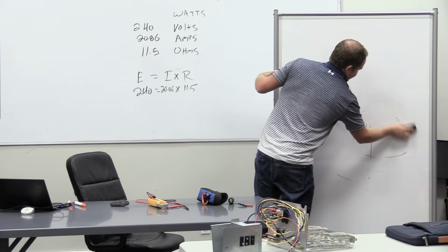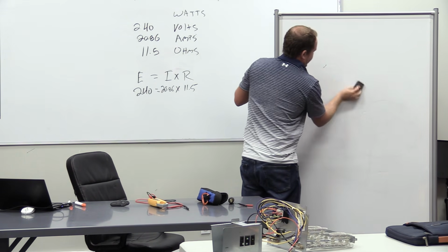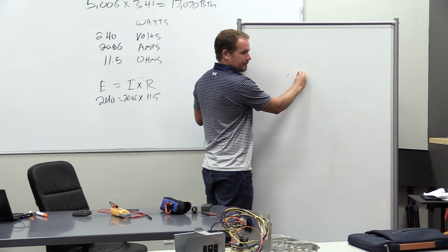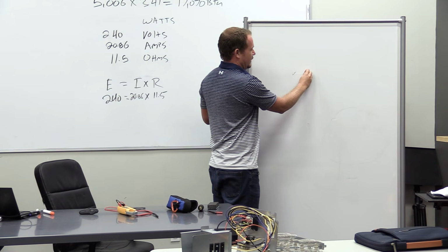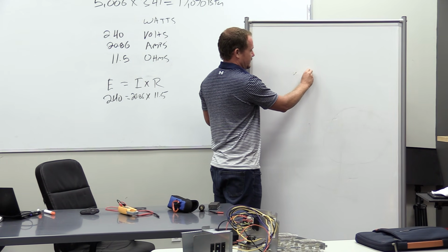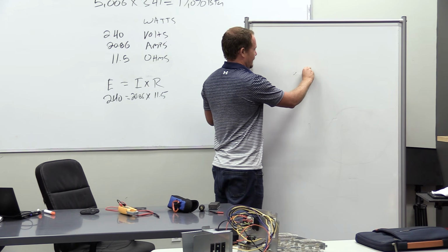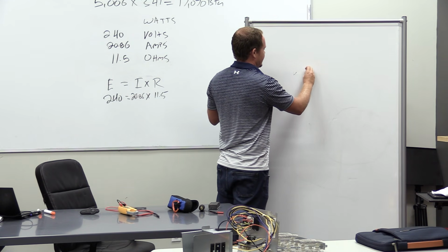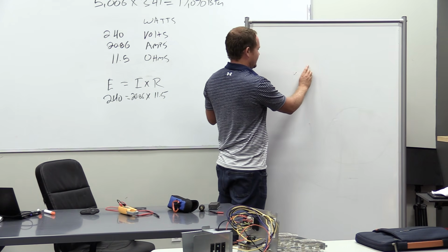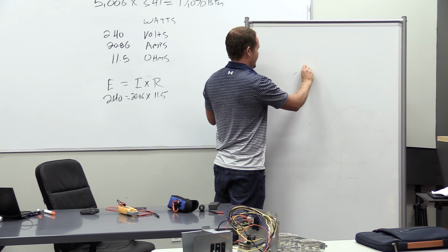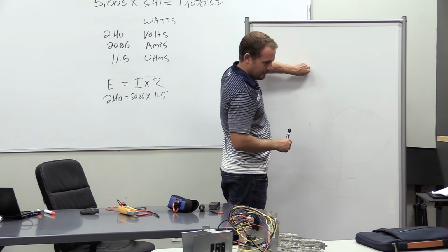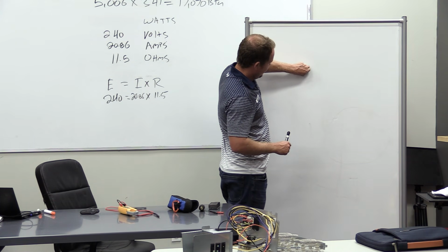Some systems have this built in with an outdoor sensor. Correct. So typically, if you were going to do this with an Ecobee, how would you do it? The Ecobee does this already through a weather app. Correct. You just tell it what temperature to lock it out at, and it does it with the weather app. Piece of cake. How would you do it with the Carrier Infinity? Well, the Carrier Infinity weather app sometimes experiences crashes. No, that's not what I'm talking about. The Carrier Infinity has an outdoor temperature sensor, right? So it doesn't need a weather app. Not anymore. Carrier Edge has the outdoor one. From the factory it has one. Well, they still use the weather app. They do? Oh, okay. Not that they need to.